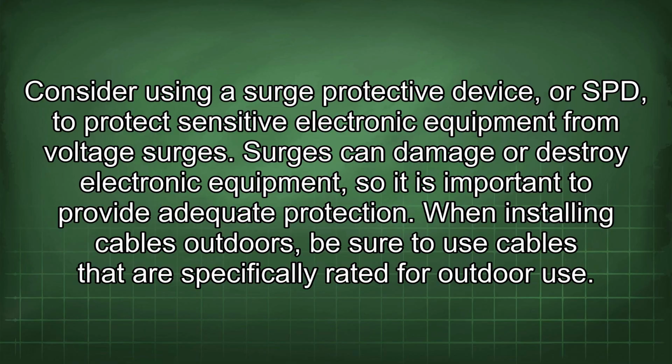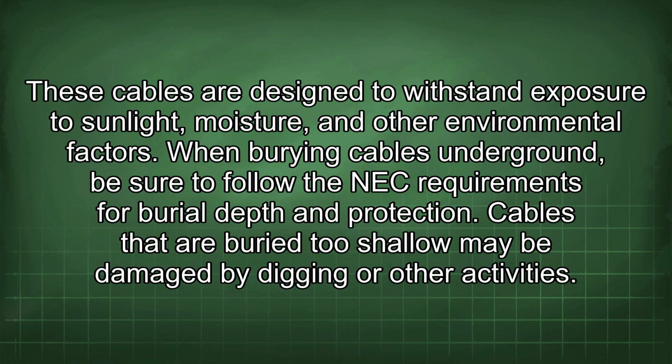When installing cables outdoors, be sure to use cables that are specifically rated for outdoor use. These cables are designed to withstand exposure to sunlight, moisture, and other environmental factors. When burying cables underground, be sure to follow the NEC requirements for burial depth and protection. Cables that are buried too shallow may be damaged by digging or other activities.